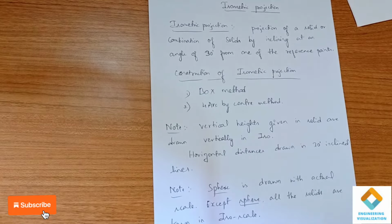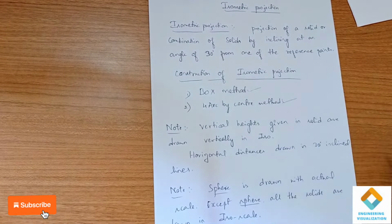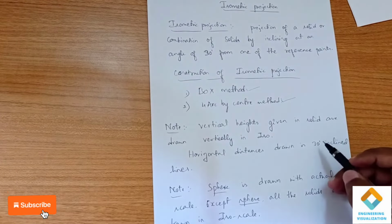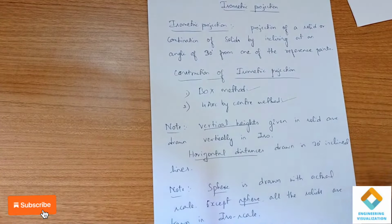So how do we construct the isometric projection? Here we have two methods. One is the box method, and one is the four arc by center method. Using these two methods we are going to construct the isometric projection. And when any one of the solids is given, it will have two distances: one is the vertical height, and the other is the horizontal distances, as given in any one of the solids.